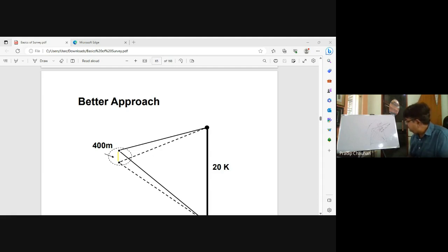and you have to acquire land accordingly. One more thing: suppose certain hurdle points are there where you are not getting your curvature. In that case, you have to restrict velocity. So it is a bottleneck. That bottleneck will restrict speed, and thereby congestion of traffic would be there.